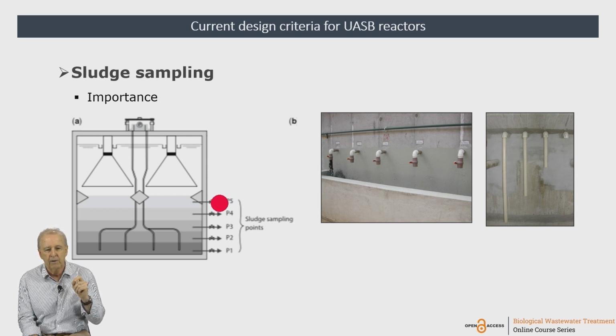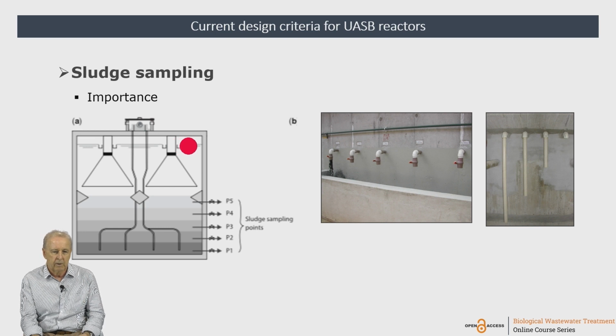If you have a highly concentrated sludge determined here, it means that the sludge can already be inside the settler compartment, and we somehow lose the capacity of estimating the mass of sludge inside the reactor. Also, with the sludge accumulated here, when we have peak flows, we are going to lose this sludge with the effluent. So we are going to lose efficiency in terms of particles, in terms of suspended solids.